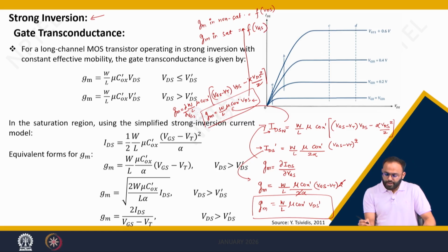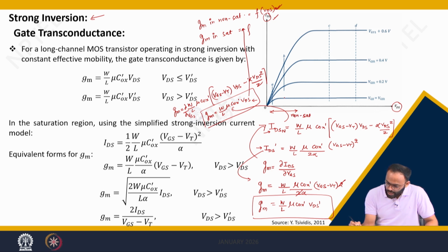We can simply identify this by this equation, and also by the output characteristic plotted here, between drain current and drain voltage. You see this region of operation is non-saturation, where VDS is very, very small. This other region is the saturation region of operation, when VDS increases beyond VGS minus VT.